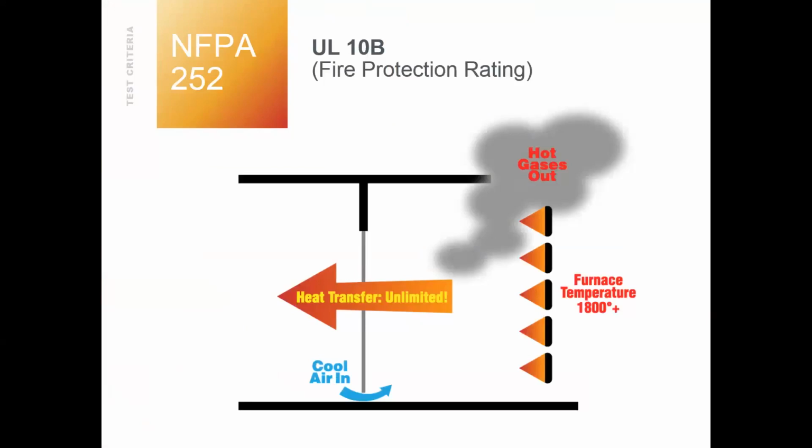If you pass that portion of the test, immediately after, you get hit with a cold water fireman's hose, 45 to 55 PSI. As you can kind of see, the cool air is allowed in, so there's always going to be some give under these rolling steel doors, especially in this particular test. And there's a damper up at the top that allows all the hot gases, the combustion pressures, to be expelled out of the test chamber itself.